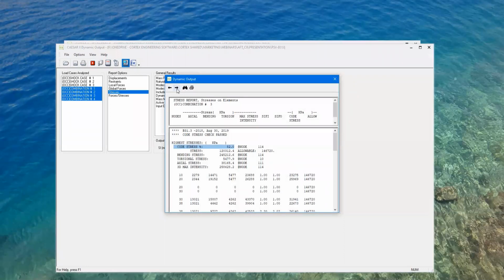And if we look at the combined case, with pipes 1, 2, and 3 all combined together, we get 86.6%. So that's pretty good. We've actually at least halved the stress by the equivalent stress method by looking at the dynamics and getting more precise load data and more precise stress analysis too, I guess.